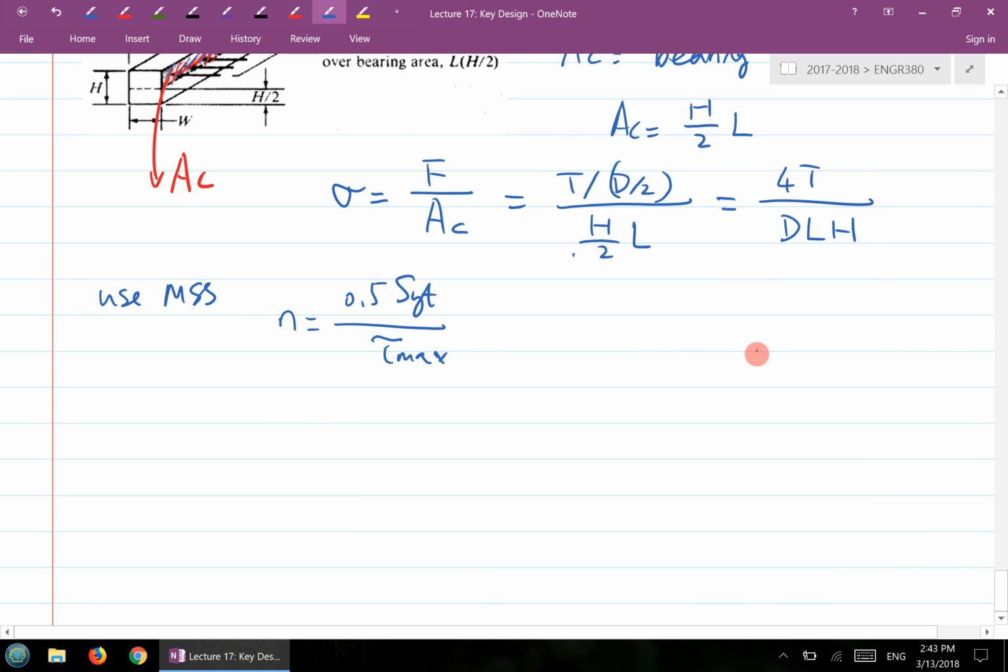For this particular example, if you take a stress element, what you see is a stress analysis for this element. There is only compressive stress, sigma, acting on both sides of the stress element. The corresponding Mohr's circle is on the left side of this plane.